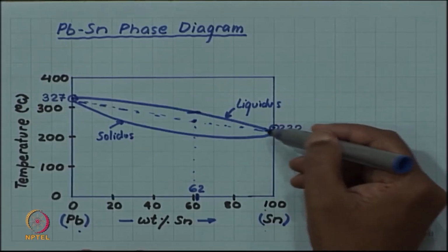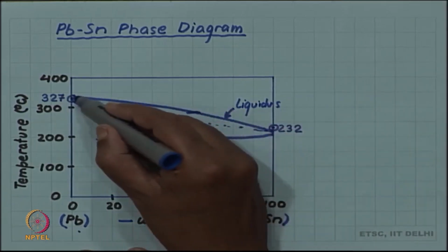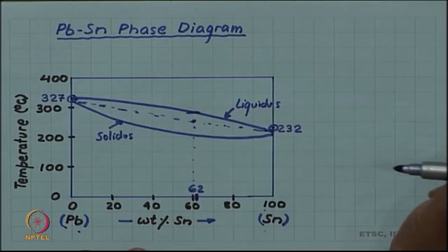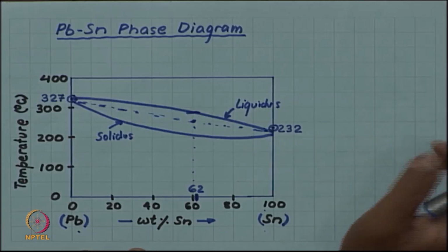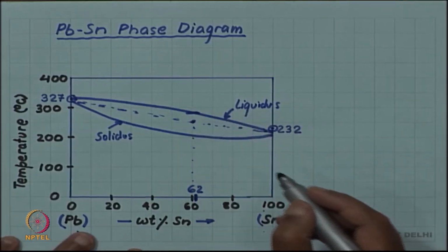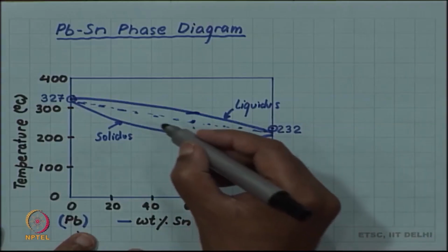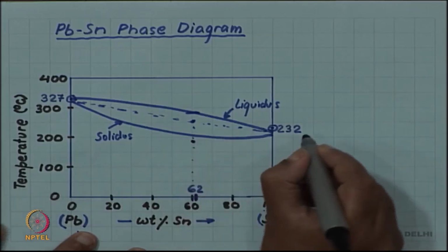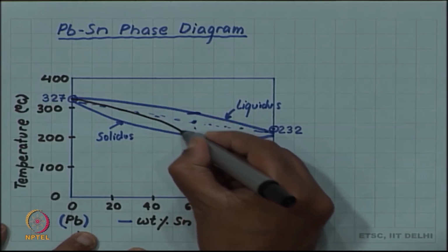So, we were thinking that we are adding low melting component to a high melting component, and that is bringing down the melting point from 327 to somewhat lower temperature. However, in reality you get an even better result, you get more than your expectation, and the liquidus is not a continuous line like this. In the lead tin system, the liquidus reaches a minimum at 183 degrees Celsius.